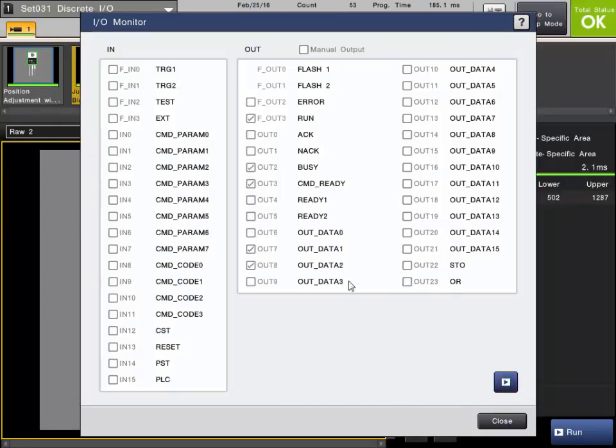So every time I trigger, it'll output the first 16, give you a STO, and then output the second 16 and give you a STO. You can see there's 2 STO pulses each time. So that's how you differentiate between the packets of information if need be.